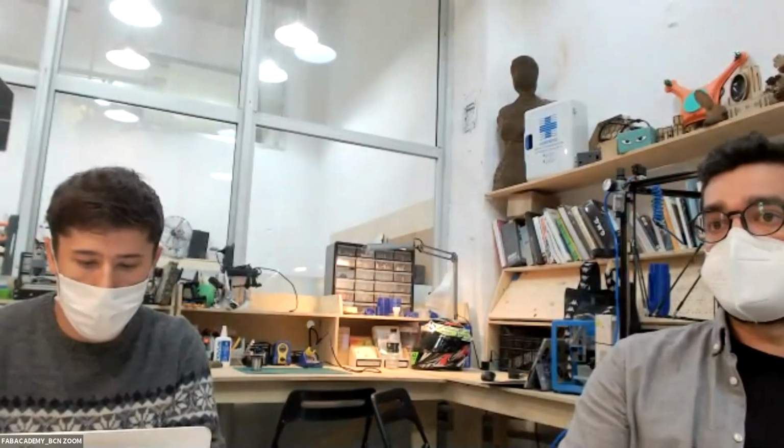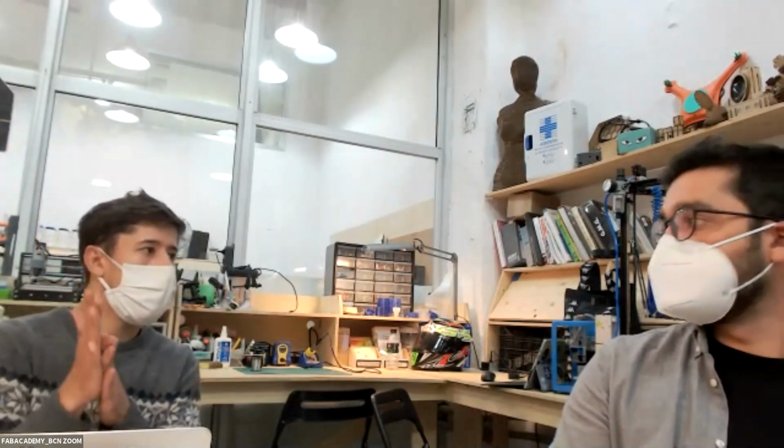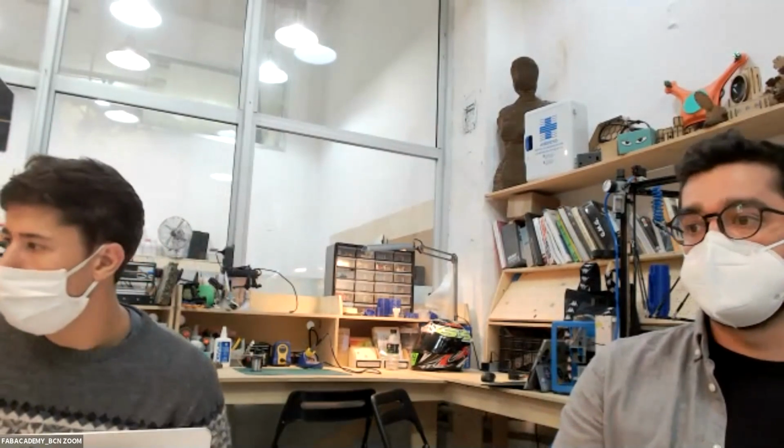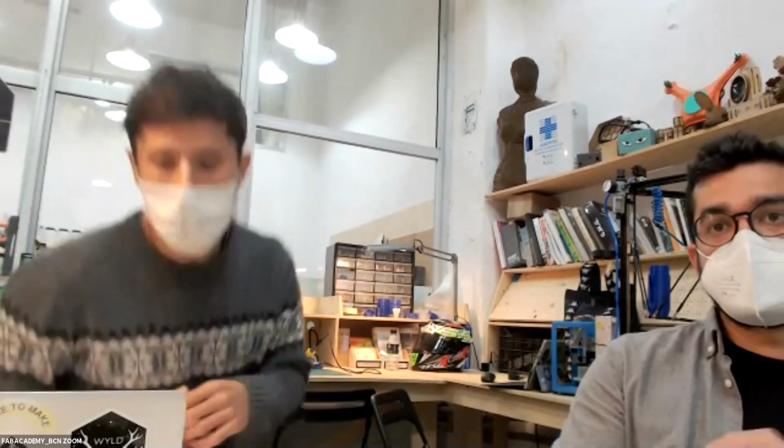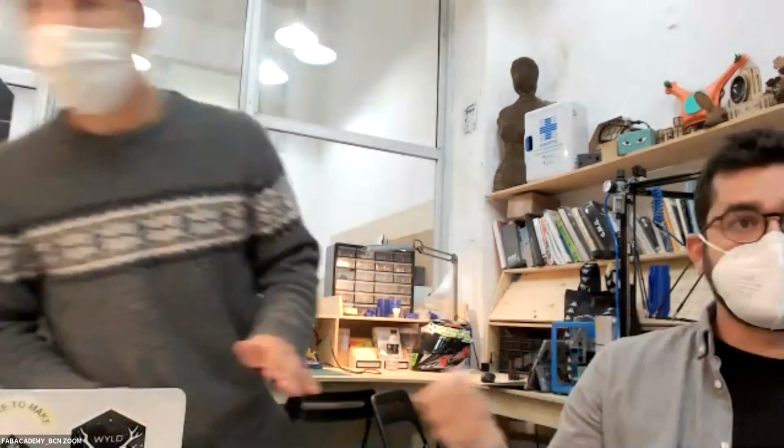Yeah. So that's, for example, one of the approaches of machines. Nowadays, maybe you have seen some Kickstarter, like this kind of thing. They say, hey, make your 3D printer a CNC, or make your CNC a 3D printer and also laser cutter, like 3-in-1 machines. That's good, but actually that's staying in the middle of nowhere. Why? Because from a basic design point of view, you want to go either accuracy and torque, or speed and accuracy. In general, you always want accuracy. So it's torque or speed.